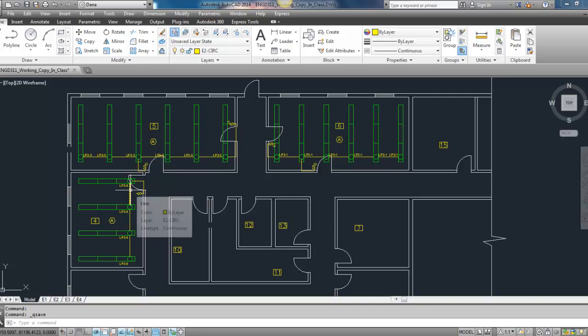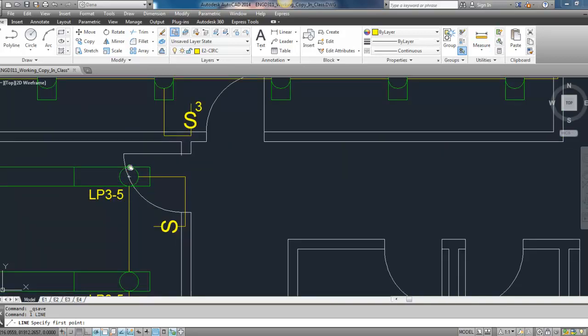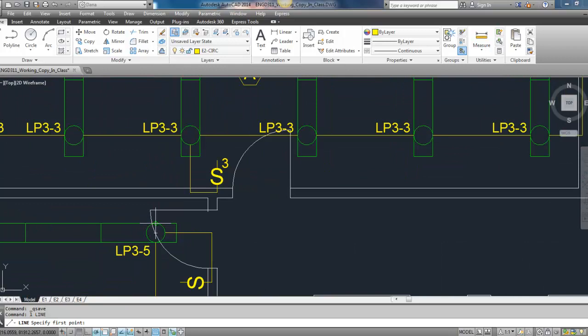That's how it's going to work: you're going to have three circuits from each phase, A, B, and C. They share the same neutral, therefore they have to be on the same conduit path. So I'm going to start at this end, the one furthest away, and take a connection from this particular conduit location. I'm going to run it this direction and connect it using 45 degrees.